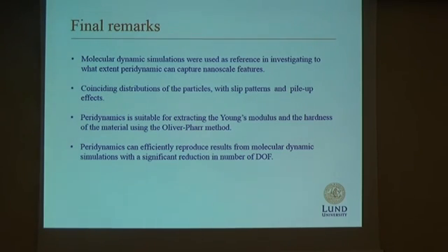What we can see from the results is quite good coinciding distributions, and especially the force-displacement curve could be reproduced in a very good way, meaning that from peridynamic simulation we can actually extract important elastic parameters such as the Young modulus and hardness using the Oliver-Pharr method, for example. And the final conclusion is that we can efficiently reproduce those results with a significant reduction of the degrees of freedom.